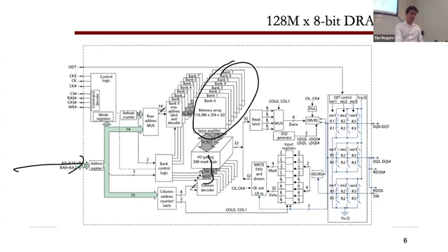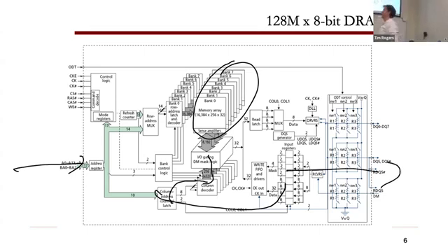This is the decoder, which is the column mux. And then there's potentially latching in here. And then eventually it goes to this I/O. All of this is the good analog stuff that happens to actually drive the lines that drive the data on the output, okay? The actual data pins are up here. This is the data, so DQ 0 through 7. So this particular chip has 8 bits that get spit out of it every time.